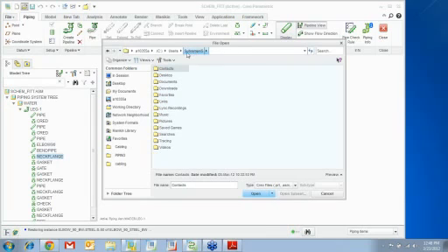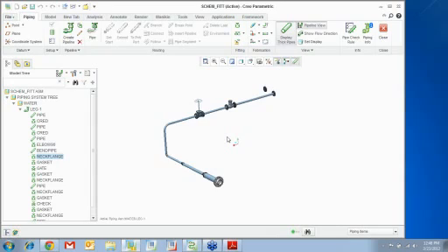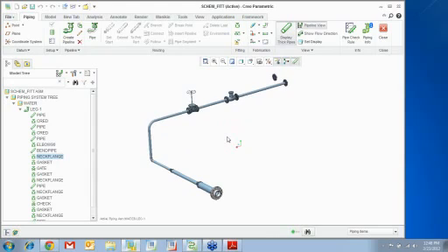I'm sorry about that, but yeah, you can actually create 2D drawings of this piping real quick. It's just like a Pro-E component, and you can also send this to a software called Alias Isogen, which will create the isometric drawings with the pipeline views and all the symbols with it. And you can do that from right here.